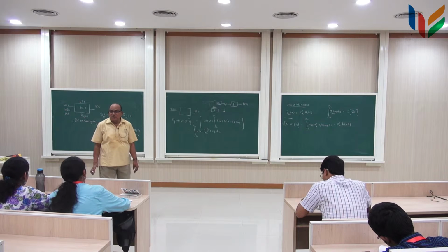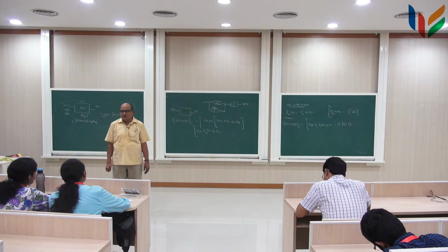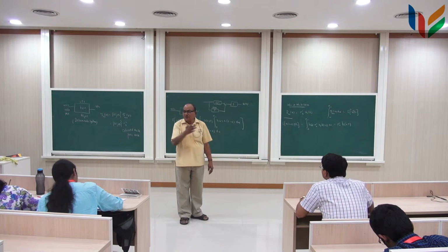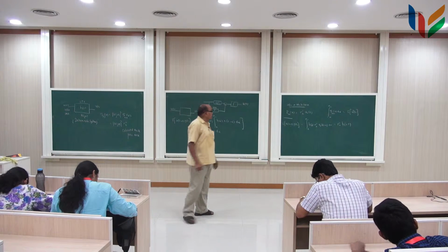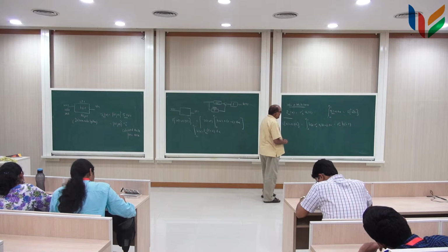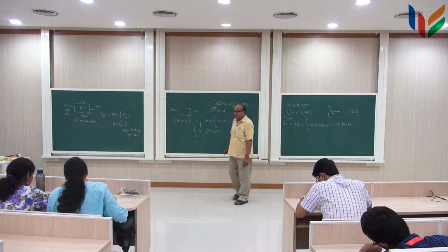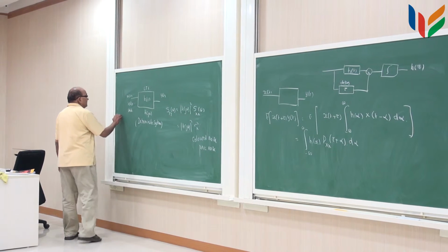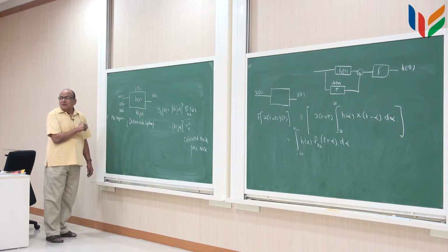You remember pseudo noise sequences which we talked about in 102? PN sequences, which are generated by putting a shift register with a feedback, and the output is a binary signal with random zero crossings, and such signals have a correlation function which is almost similar to this. There are other signals also, but the most commonly used signal is a PN sequence. Are you with me or not? If you don't, I'll repeat it.